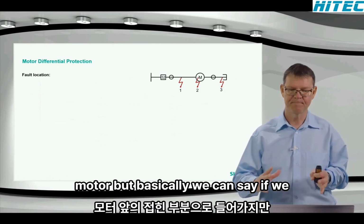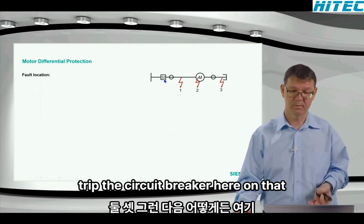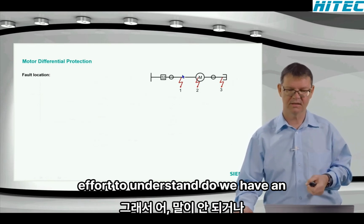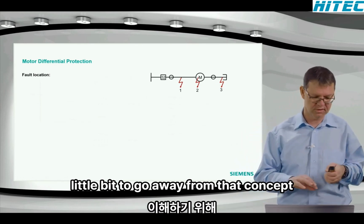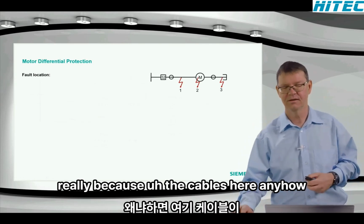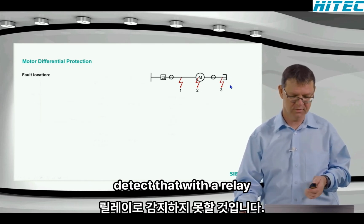But basically we can say, if we have a fault here somewhere on the places 1, 2, 3, then we must anyhow trip the circuit breaker here on that place. So it doesn't make sense to spend a lot of effort to understand, do we have an internal or external fault? So we have to go a little bit away from that concept here. Besides, the fault here on the position 3 will not be a fault really, because the cables here are anyhow short-circuited behind the motor. So if I have a short circuit here, I will not detect that with a relay.